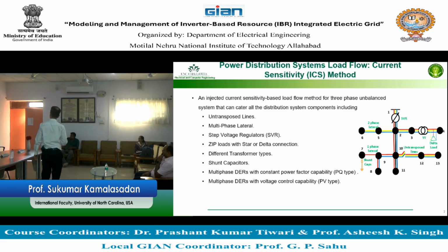Distribution lines have voltage regulators. Distribution voltage regulator, step voltage regulator. Distribution lines have ZIP load. Distribution lines have different transformer connection types, Y connection, delta connection. Distribution lines have shunt capacitors. Distribution lines have multi-phase DER with constant power factor capability and voltage control capability.